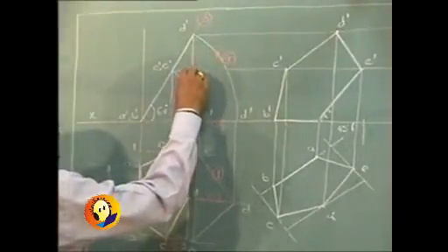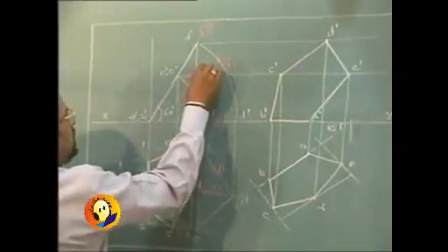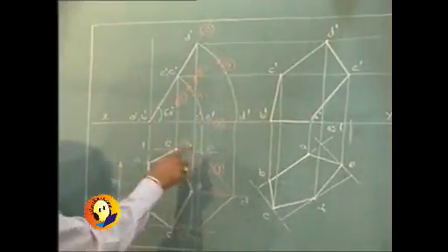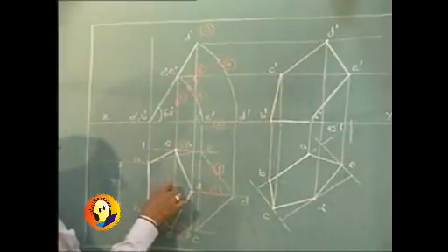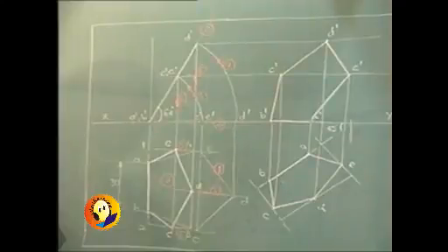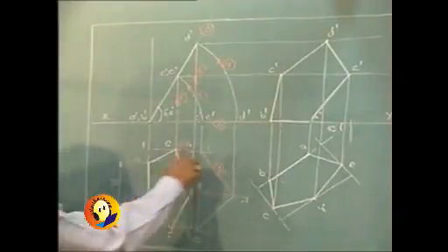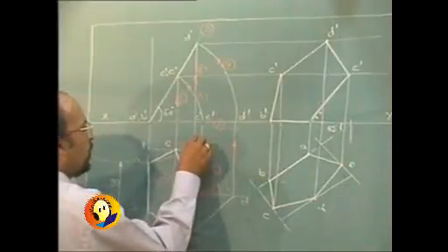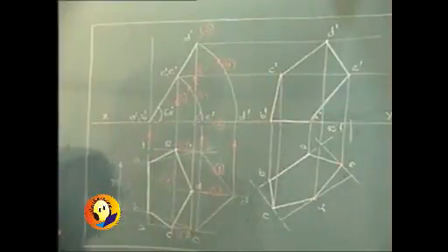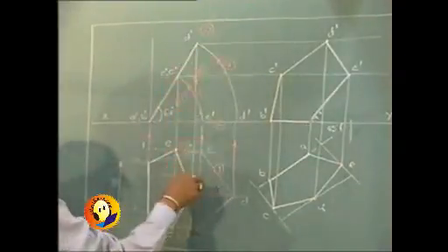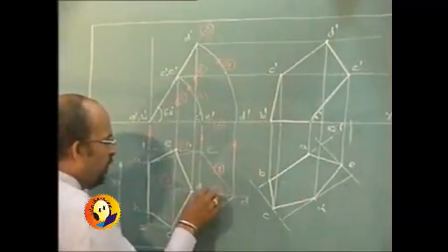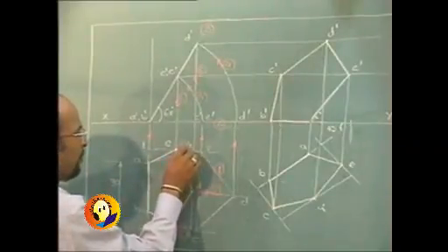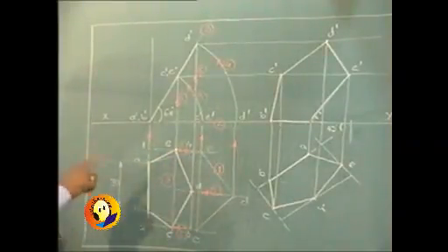Dropping the projectors was step number 6. And drawing the final shape was step number 7 with darkening. So the figure is drawn, then it was projected up to obtain the line view. Line view is rotated, points are taken down. It has resulted in movement parallel to XY in the other view, that is in plan. And we have finalized the plan.